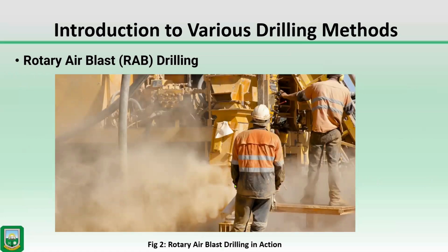So this is an air blast drilling in action. The dust confirms the presence of compressed air that is being used. You can see how dusty the area is. That means that the cuttings that were inside the borehole or the drill hole are being blown up by compressed air to the surface.